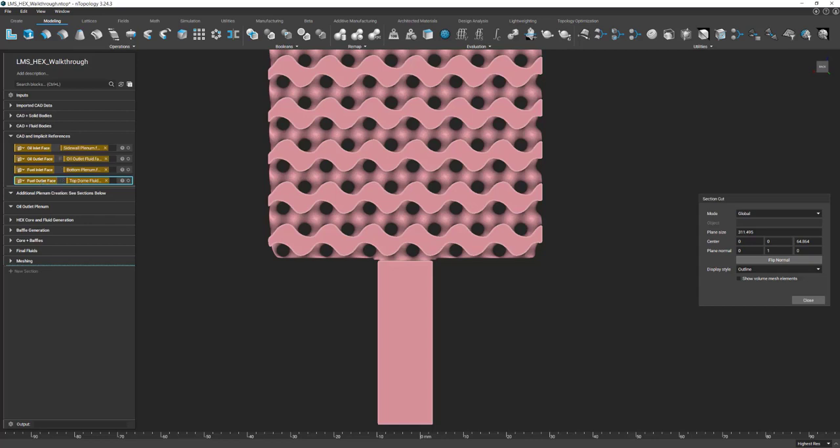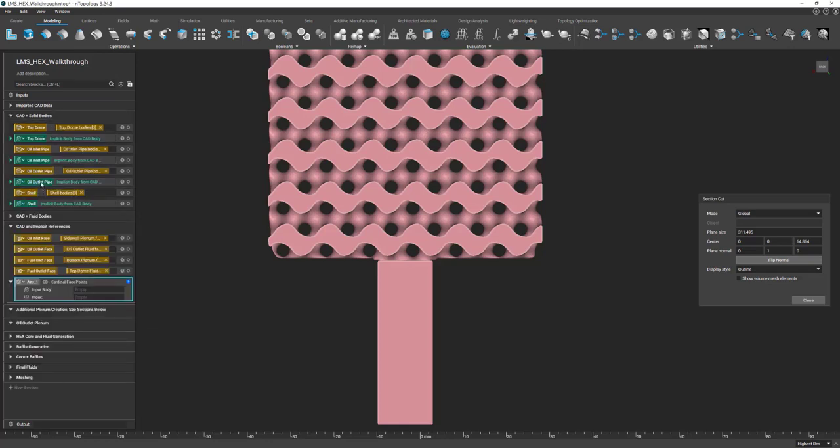And I'm going to call on the cardinal face points block. So I'll start to type cardinal, and I'll get the custom block that's cardinal face points. I'm going to make this a variable, and the input body in this case is going to be my oil outlet pipe. All this block does is it goes to the bounding box and captures the centroid at one of those faces of the bounding box.